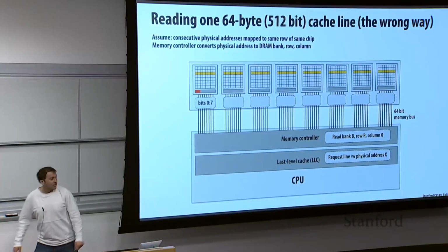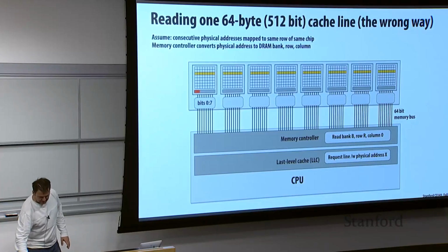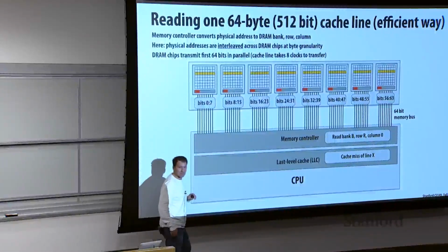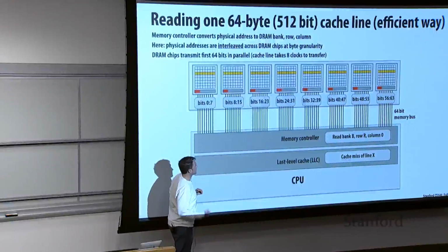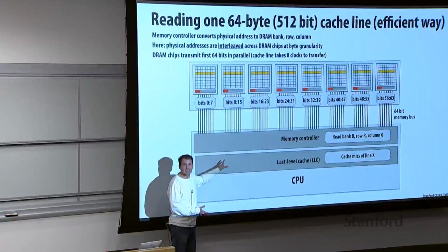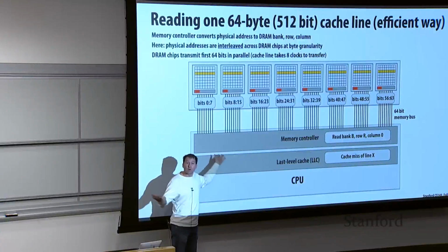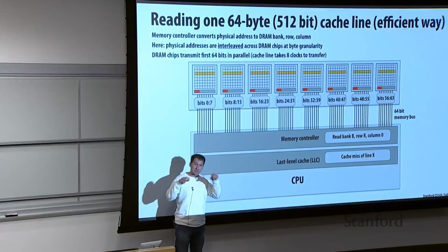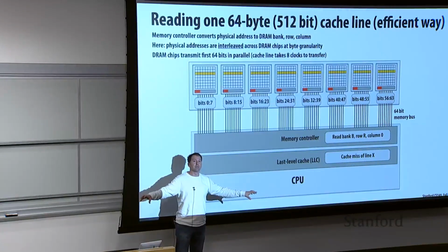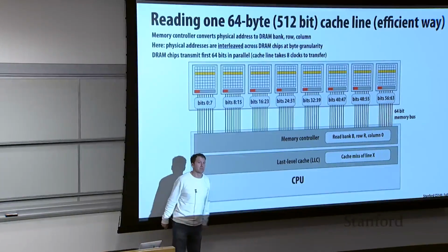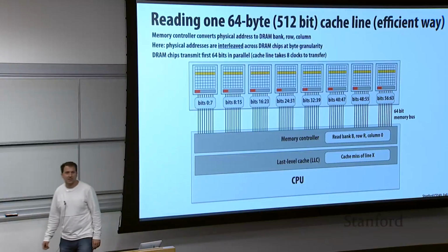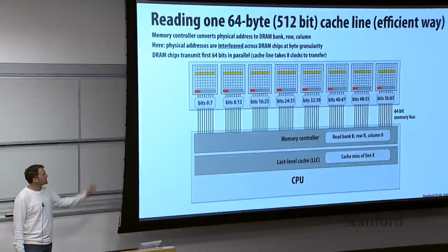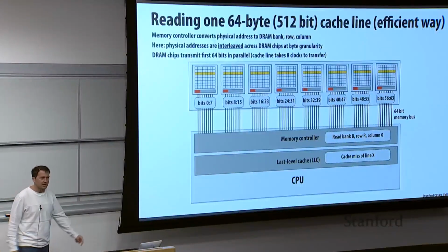Right? And so now keep in mind that if I do this, let's say I stride my bytes across the DRAM chips. Does it make sense that we're going to get 8 consecutive bytes here? Right, okay. So, but we have a whole cache line, right? We need the next 8 bytes. So I would probably put the next byte, interleave it amongst the DRAM chips, but put it in a different bank on those DRAM chips, because I want to initiate that row access to the next byte immediately in the next cycle. Yeah, I should change that diagram to show that there's a couple of banks under each of these.